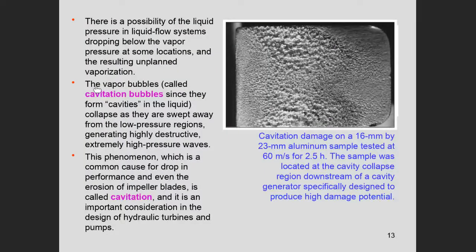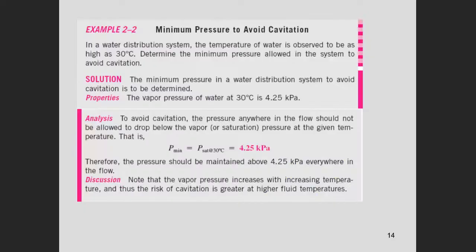Now, cavitation is a very common problem in pumps. Okay? A pump was supposed to work at a specific pressure in order to push the water at a specific temperature. If the pressure drops below the saturation value, cavitation will take place, and you are losing both power and quantity. Okay, there is an example here.